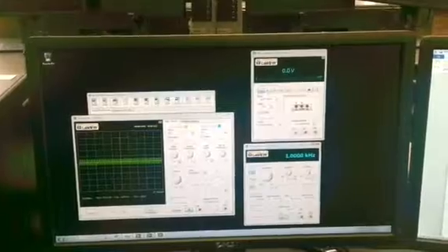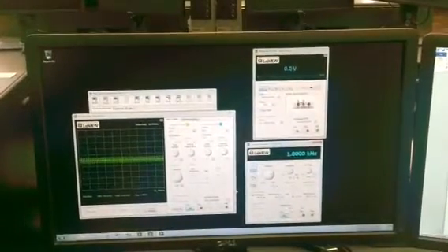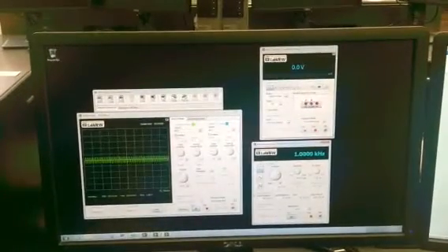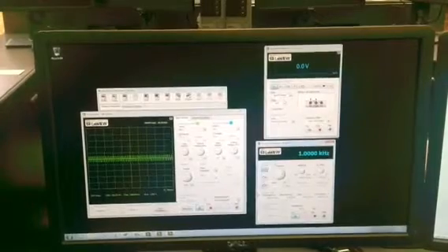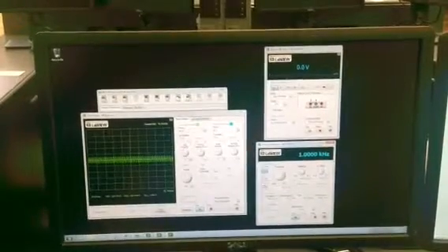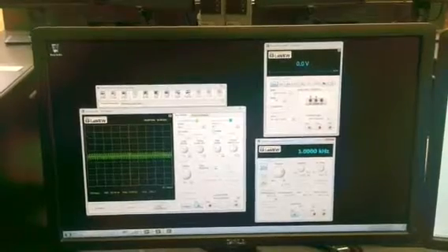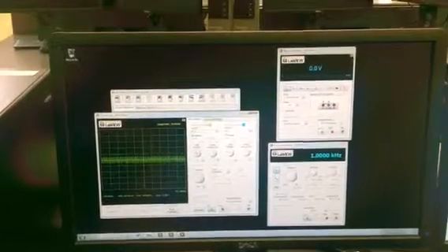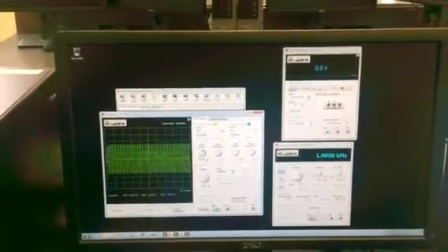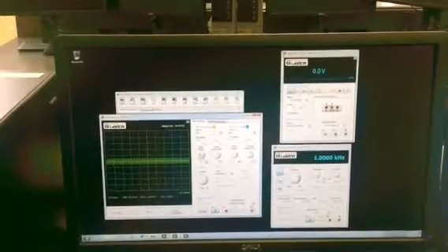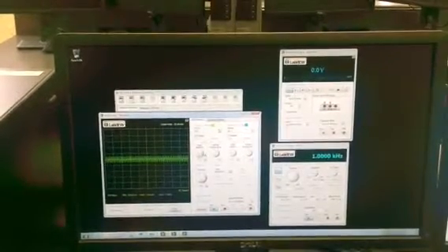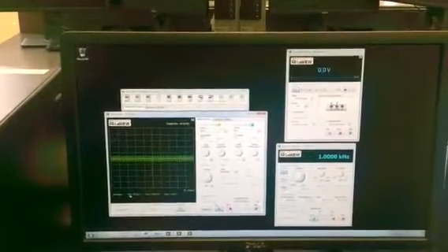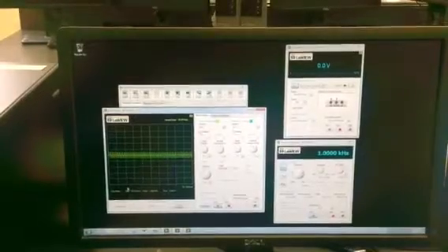For the following functions, adjust the time base and voltage division controls on the oscilloscope so your screen closely resembles the corresponding figures. Make sure to adjust the function generator DC offset to raise and lower the average value of each time varying voltage and observe the effects on the oscilloscope screen. You can get that from over here on your oscilloscope using the scale. Then for each of the following functions, calculate the theoretical RMS, and then you can find that RMS value down here and record your findings.